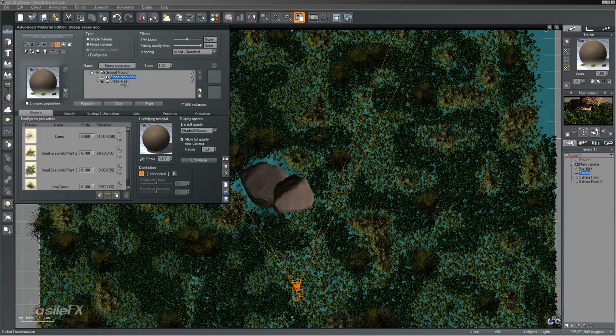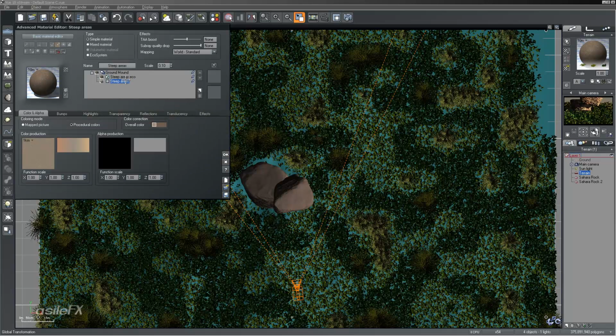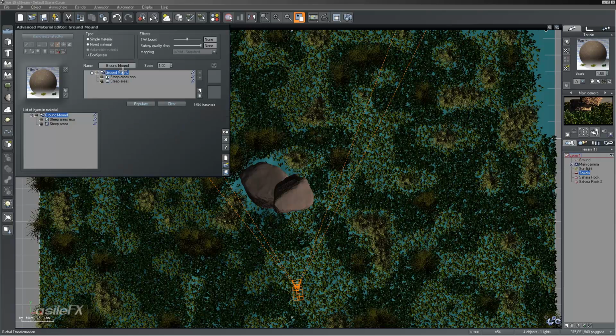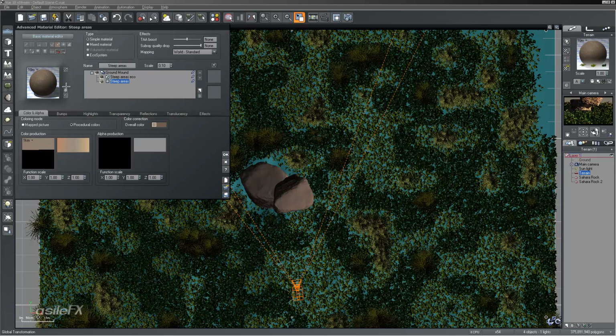It makes it a little easier, and then go in and define the individual scales separately, which is why I had originally changed that from 0.1 to 1, because what it would end up doing otherwise is changing the overall material scale to 1 and then changing the steep area probably to 5, which usually ends up happening, or 2. Sometimes it can vary depending on the material and what its original size was.